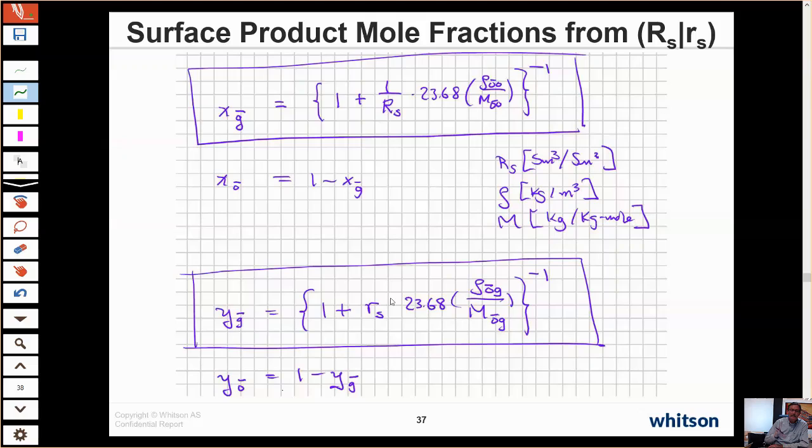The black oil model is a compositional model, and it does a phenomenal job of describing, as Singh will be showing here in his presentation, complex reservoir simulation processes of very complex near critical oils, near critical gas condensates, retrograde condensates. What you see is that you're able to describe for sure 99% of all depletion processes for any kind of fluid type compositionally with a black oil model. It's been shown by Keith Coates, originally in 1982. We have a couple of papers on it ourselves. It is a compositional model. It's a simple 2-component model. But it's a special 2-component model.